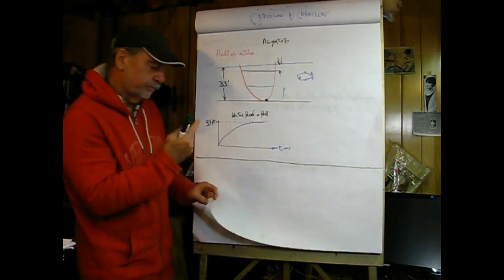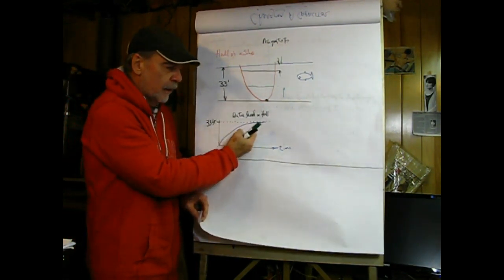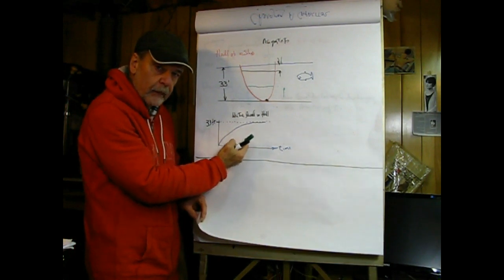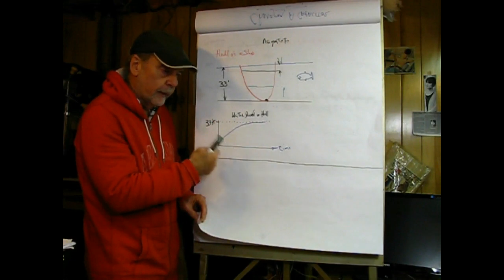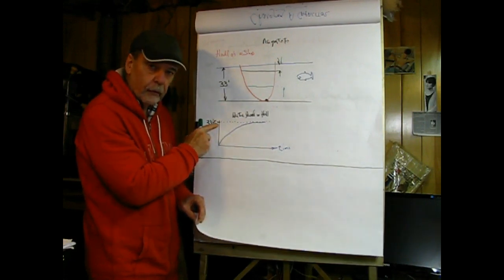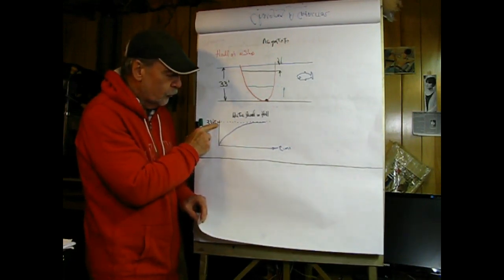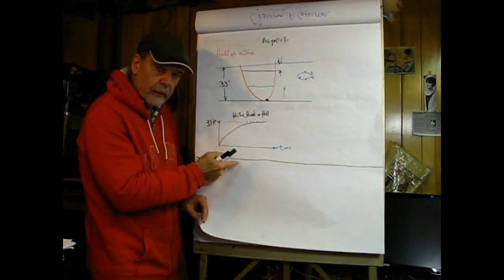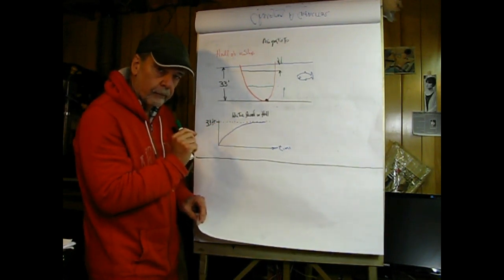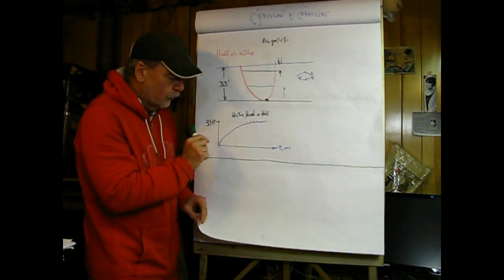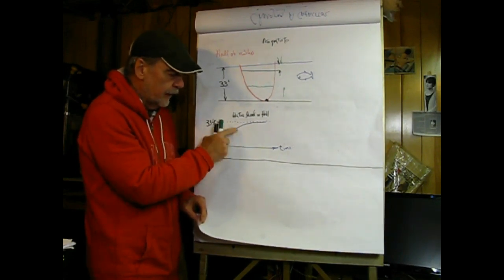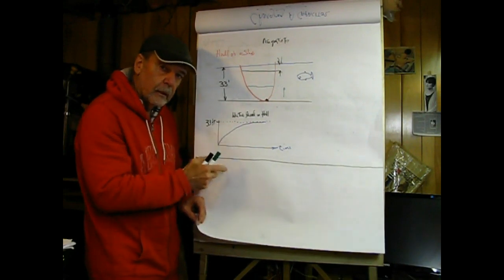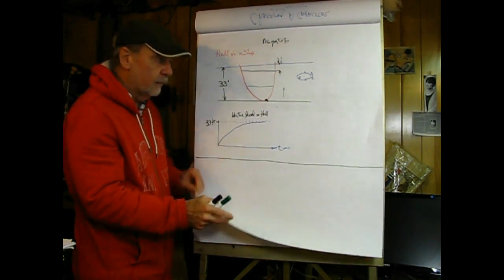Also, concrete hardening has a shape like this too. Only this is going to be the theoretical hardness, which is determined by the chemical mix of the cement and so forth. So what this means is when you get up tomorrow morning, your sidewalks and driveway and so forth are going to be a little bit harder than they were the day before. So that's why they keep cars off the driveways initially for like 6 or 7 days, so they can get up in hardness where it won't crack if a vehicle drives onto it.